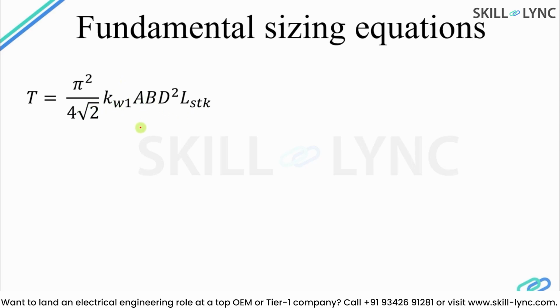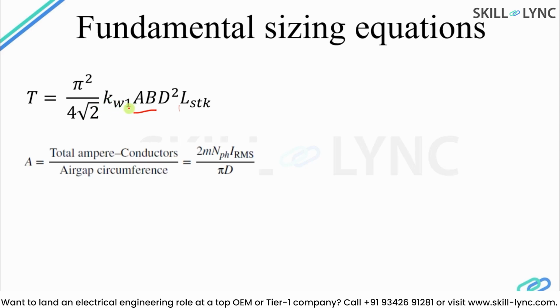This torque equation involves A and B, and D is the diameter, and this torque is proportional to the square of the diameter. L stands for stack length, so L_STK stands for stack length, and we are going to see the term KW1, which is the winding factor, the fundamental winding factor. So 1 stands for fundamental.